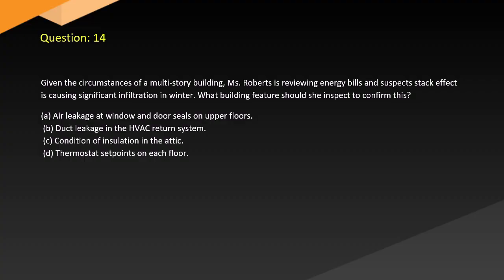Question 14. Given the circumstances of a multi-story building, Ms. Roberts is reviewing energy bills and suspects stack effect is causing significant infiltration in winter. What building feature should she inspect to confirm this? A. Air leakage of window and door seals on upper floors. B. Duct leakage in the HVAC return system. C. Condition of insulation in the attic. D. Thermostat set points on each floor.